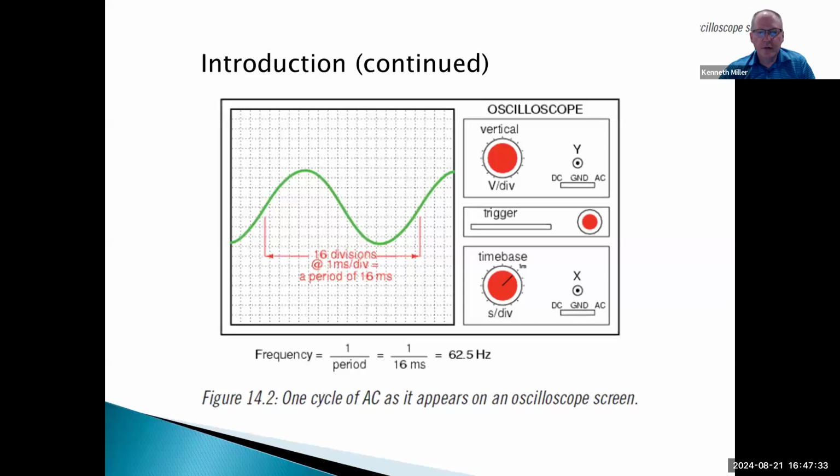All right? Now, the device that we're going to use to generate the signal will be the frequency generator. Okay, so that's a device that we have in the lab, or you'll sign one out from the stockroom, and you program it so that if the lab says a 10 millivolt peak to peak at 100 kilohertz, you would set that up and then put that into your circuit, and then you would put your oscilloscope probe on the input, and you would see it on your screen here.